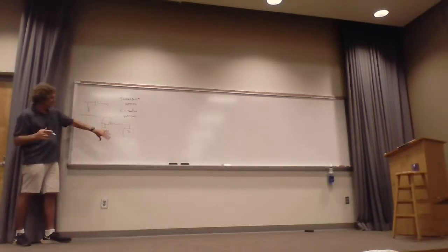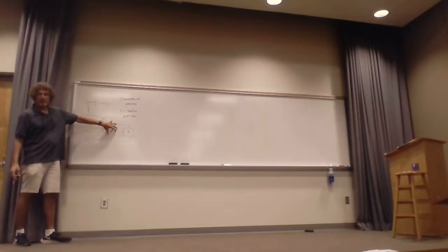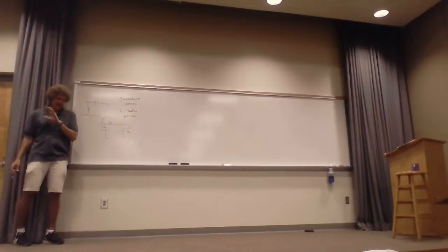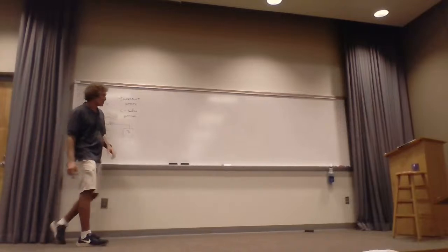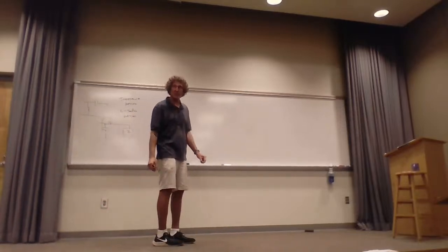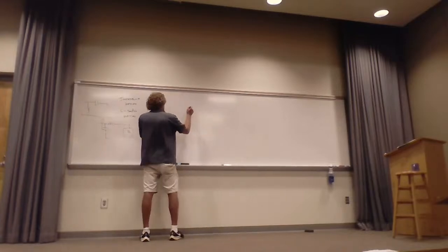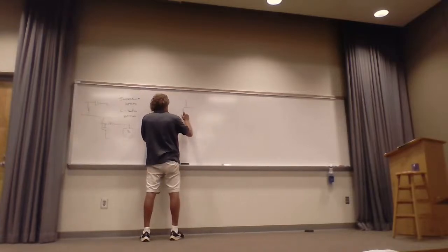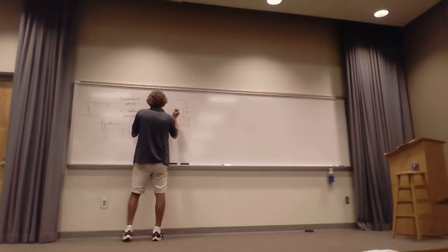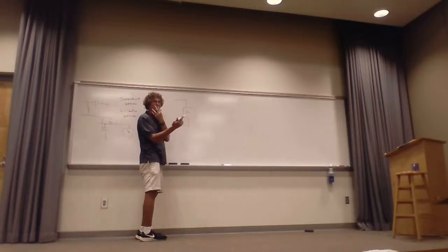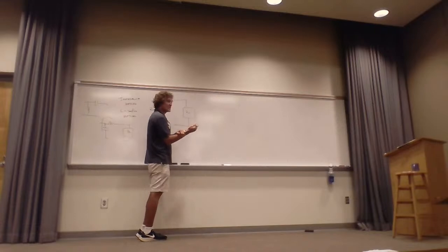In other words, all the elements you add are right at the load. Got that? There is no, I gotta move so far, which is real important. I mean, there is no long stubs. Everything is gonna be attached to load. So let me go through this with you and why it's so important. So if I have some impedance here, ZL, and I want to impedance match it to something Z naught, but I don't want to move and have shunts and stuff like that. What I do is this.